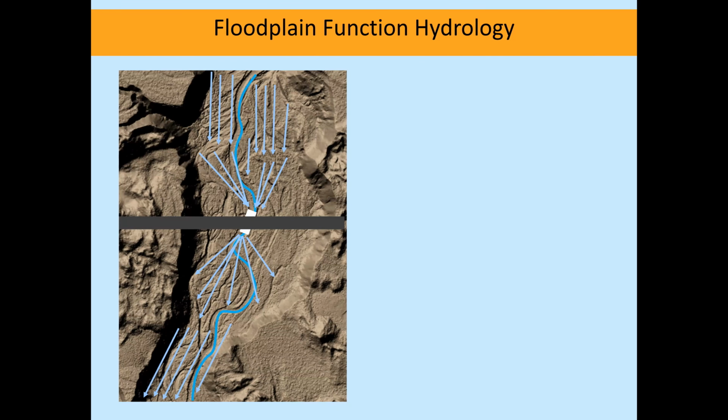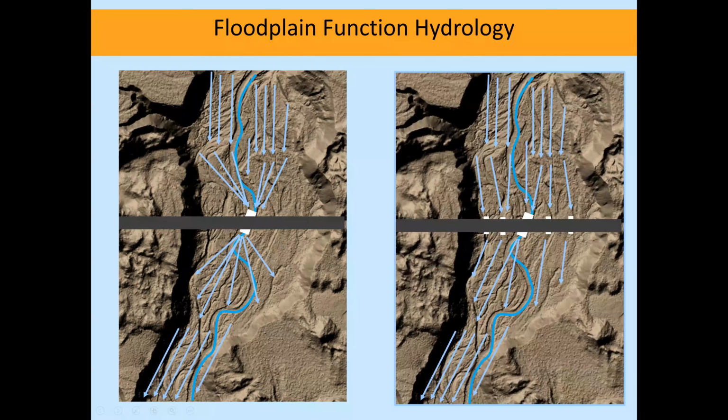So you could have sediment deposition upstream of the culvert as that backwaters, and then a bit of a hydraulic drop as it enters that culvert because there's just so much flow coming off the floodplain that has to make it through your culvert. And a good idea is just to account for that, have some floodplain relief culverts, or maybe just site, in this case, it looks like a pretty dynamic system, you would just site a bridge that spans that whole thing in a narrow spot, something like that.